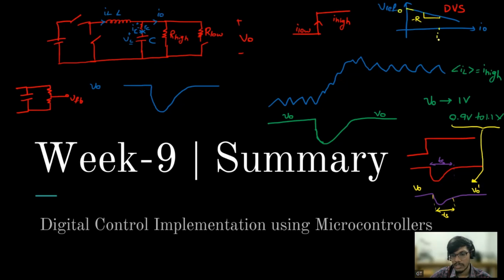At I naught equal to some I1, the new V reference will be V reference naught minus R into I1. This curve is decided in such a way that our V reference will stay within this region, and this linear curve will be extended from light load condition to high load condition.